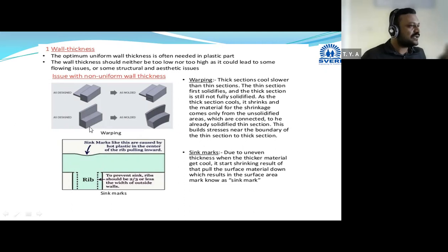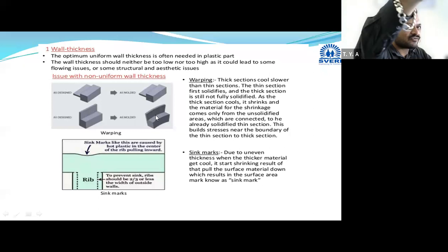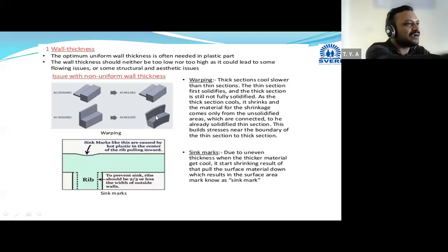Then after cooling, as this portion is thick, no problem will be there at this portion. Means it will cool on time, or it will cool rapidly as per we desire. But in this thick section, what will happen is the corners, the surface layers, will cool rapidly, or initially they will solidify and they will pull. They will try to attract the material from the other areas, as solidification will start at the corners. From end corners, it will go to the center.